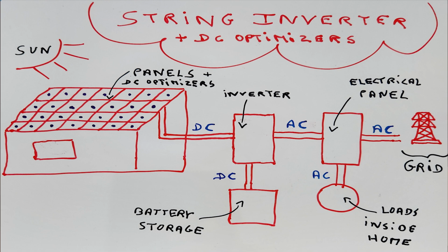We also have a much more efficient system, especially when compared to microinverters. Let's say that you have a battery storage. The DC power produced by the solar panels can be used directly to charge the battery without incurring any conversion. And so, charging and discharging the battery would only trigger one conversion from DC to AC electricity. Unlike the microinverter configuration, which incurs 3 conversions, also known as the triple conversion loss penalty,